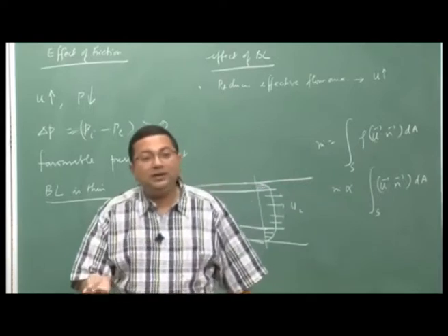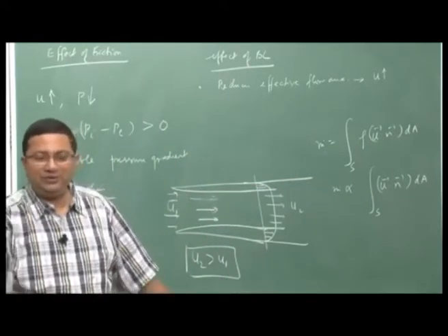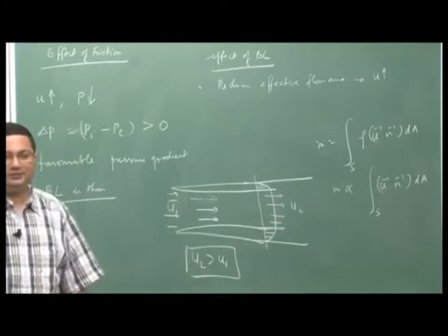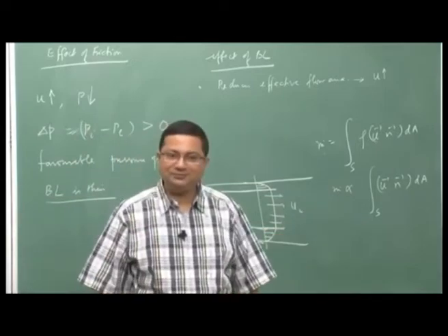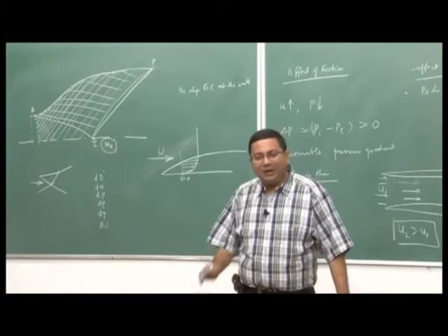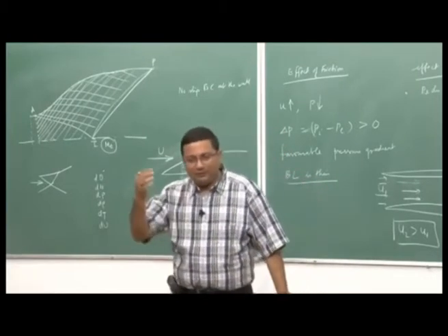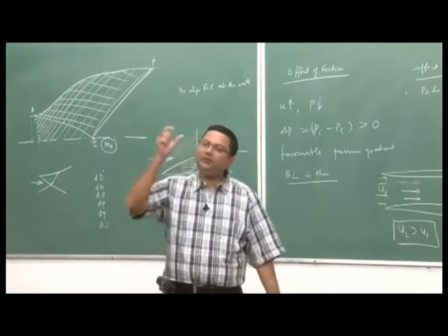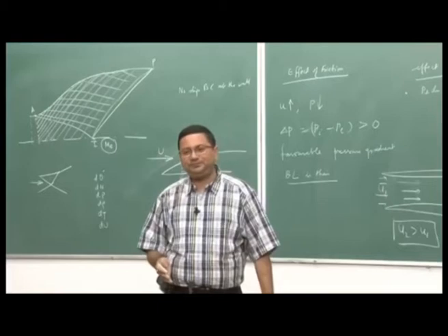As the velocity increases, your Mach number increases, right. Then every property is going to change, because we have defined those things as a function of the Mach number, but now your wall is fixed, now your wall is not changing, you have already designed it, right. So, now it is no longer isentropic, the assumption that you have made, because that was based on isentropic assumption, for a fixed contour there was a fixed flow property.